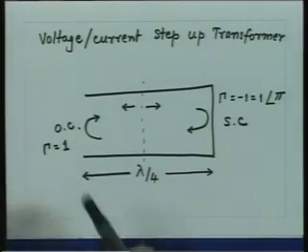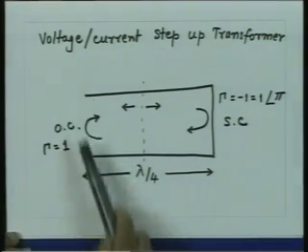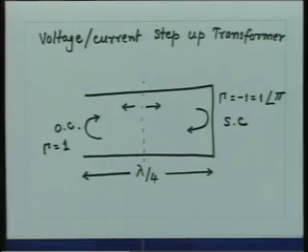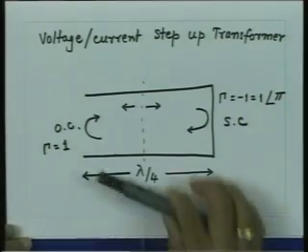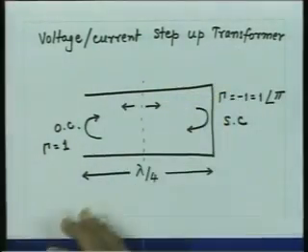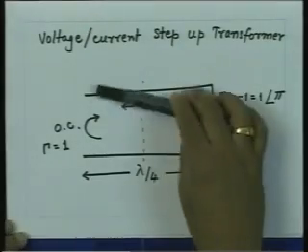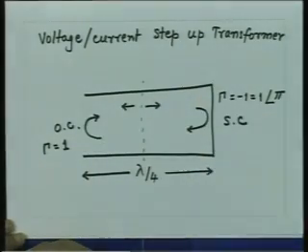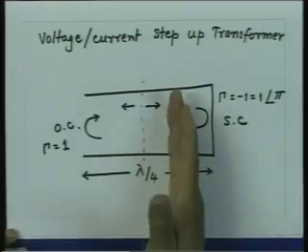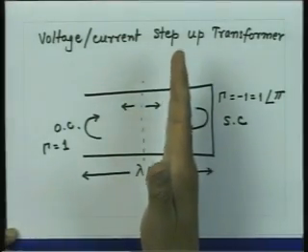So, if there is no loss of the transmission line, ultimately in the steady state the voltage will reach to infinity between the terminals of the line. However, in practice it does not happen, because when the voltage and the current starts growing on the transmission line, the ohmic losses also go on increasing, and when the loss in the line because of the resistance and the conductance becomes equal to the energy supplied by the coupling source, at that point there is an energy balance now, and the growth of the standing wave on this section stops.